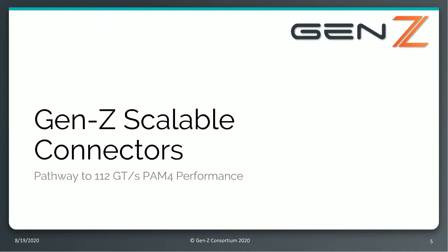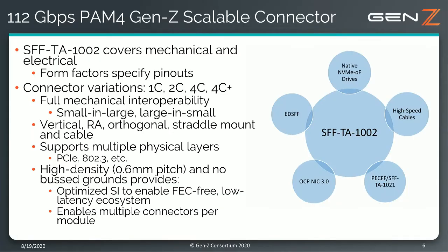to these trends. The first section that we're going to look at is the Gen-Z Scalable Connectors, originally defined by the Gen-Z consortium and now a part of SNIA. These do provide a pathway to 112G PAM4 performance.